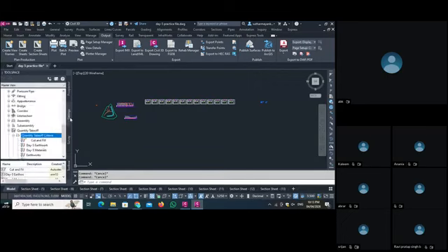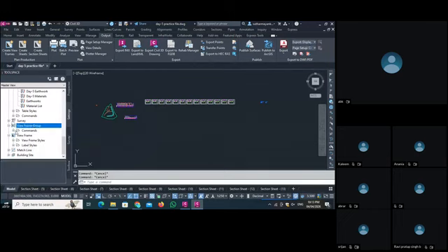Okay, then we go here to the settings tools. See, you can manage this view frame and sheet section from here also. You can set the label style from the view frame. You can set the view frame group also. You can set all your view frame sheets from here.